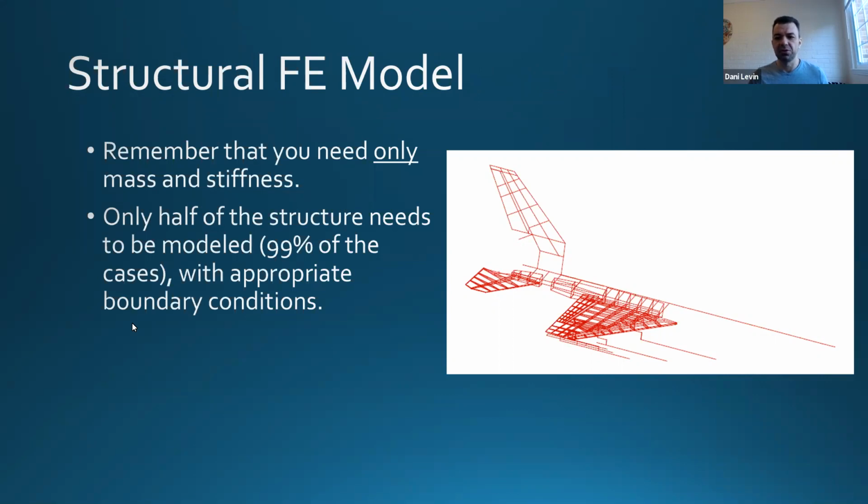And yeah, it looks really awkward for non-structural guys. Usually this model is harder to build than a very complicated finite element model, but it saves you a lot of time and reduces the size of your model. So when we talk about a structural model that is suitable for aeroelastic analysis, we're talking about this very condensed model with beam and shell-like structures, elements, sorry.